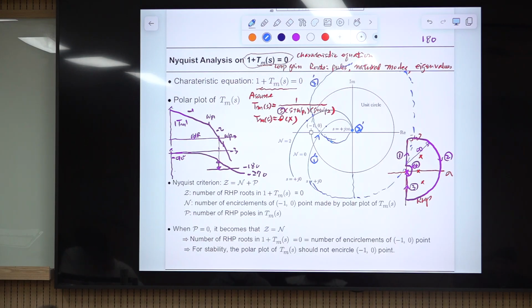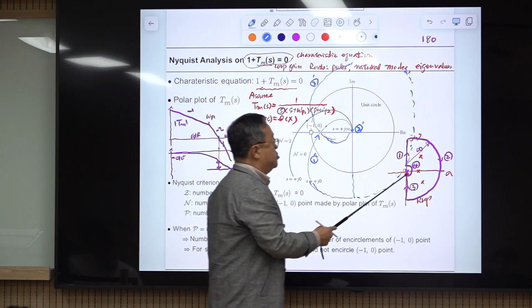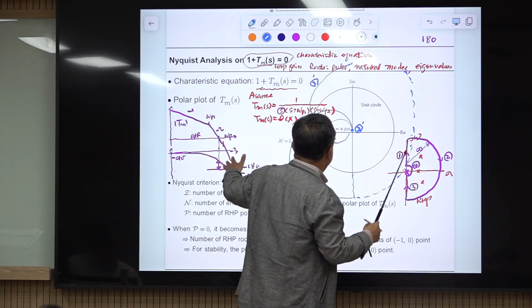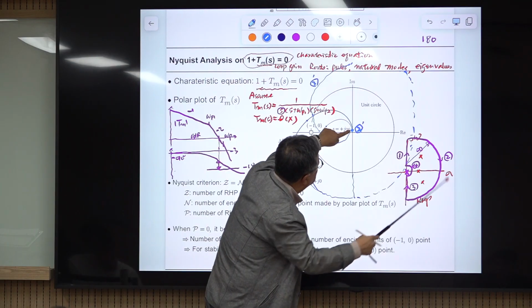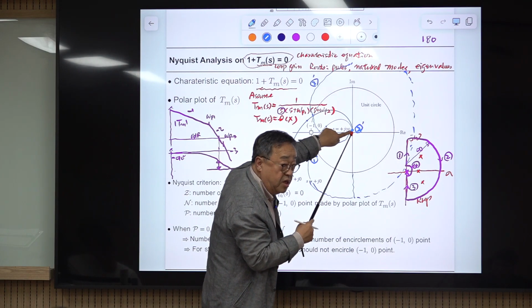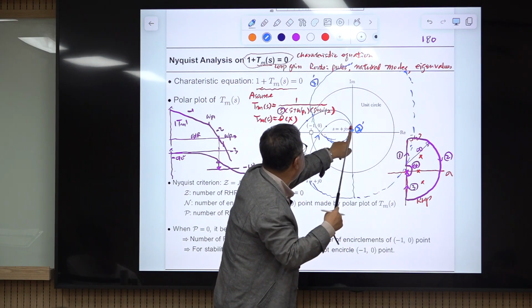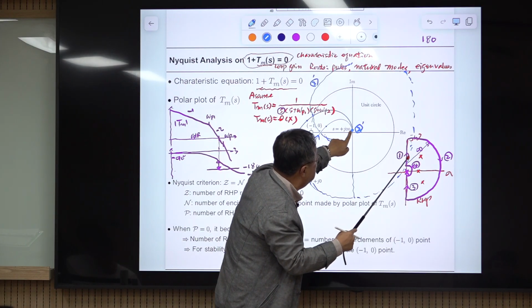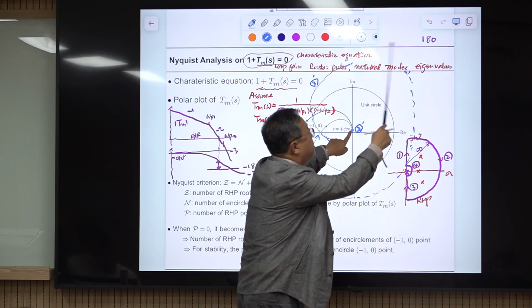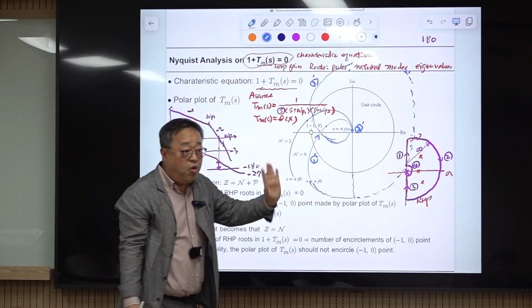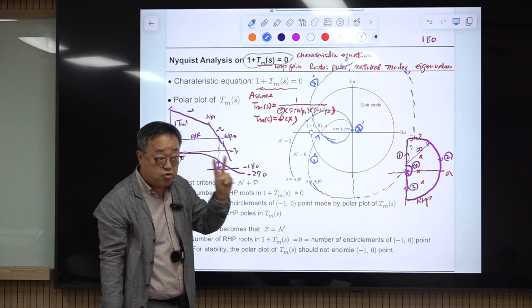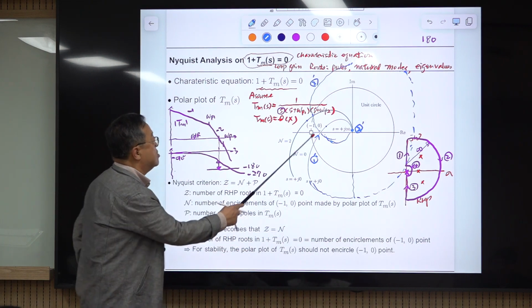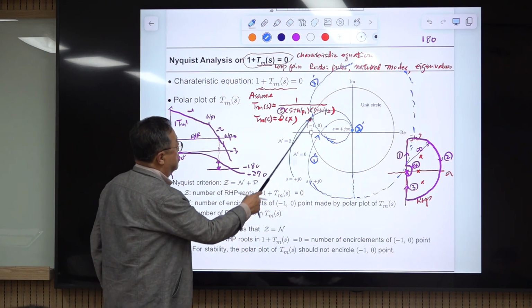It should come back like this. All right. So if you travel along this Nyquist path, doing some mapping, you know this part, and this part is collapsed to this one point, and this part is just a mirror image of this, and this part is just the infinity line. So no detailed knowledge is necessary at those two regions. So now you have this, right?